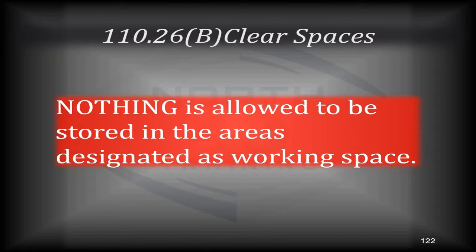However, it can be in the same room as the electrical equipment as long as it's not in the working space, and if parts that are normally enclosed are exposed only in the event of needing repair or checking, and they're guarded. So if you've got parts that are normally going to be guarded and are only exposed for inspection and repair, you're good to go.